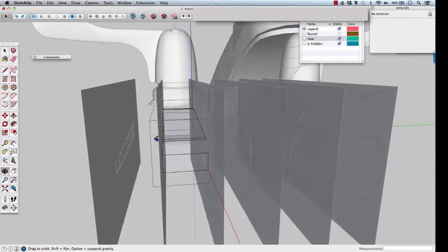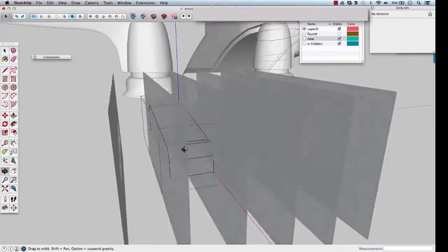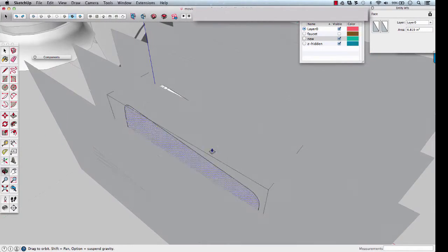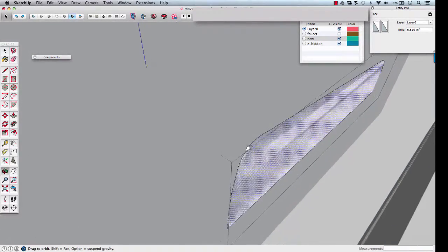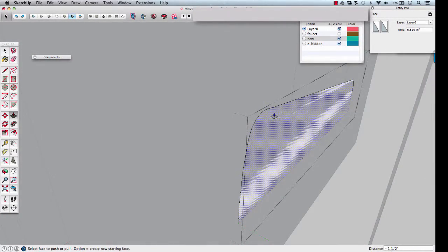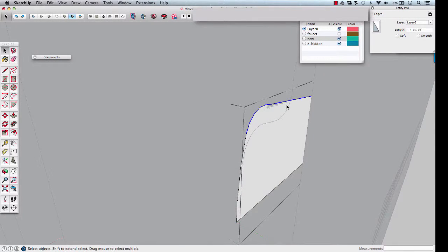That's now 1/6 of our modeling effort. Now we'll adjust our geometry to match the other profile. Select the top edge in this curve, and we'll move it down till it matches that curve. If we move it in the blue, start going down to match it.